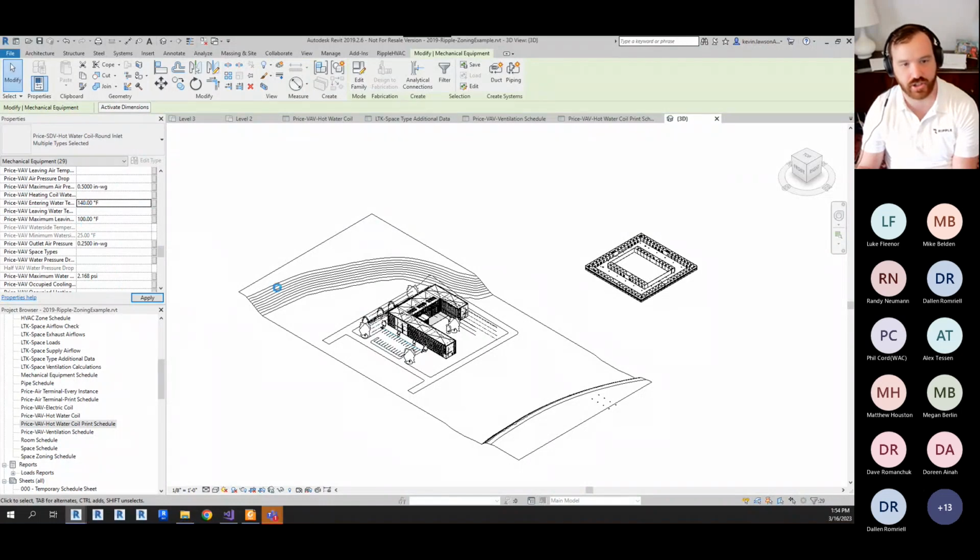So what this is actually going to do is it's going to go up now, and it's going to recall the selection software and reselect all these coils at 140 degrees, and then modify the family size, the coil count, the GPMs, modify everything in there so that you'll get a good coil count.